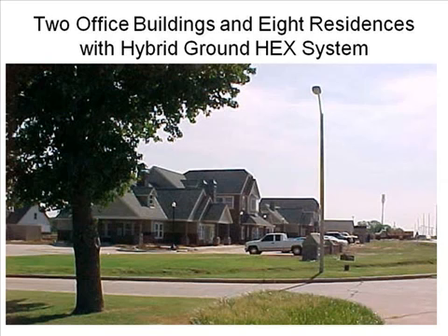Because each one of these offices has a different landlord, and each house has a different occupant, a single circulator is placed on each heat pump, and there is no primary and secondary one. The only costs that are absorbed by the building owner, which is just one, is the fan power and the pump power on the cooling tower. And so what you're able to do is parcel out those energy costs.